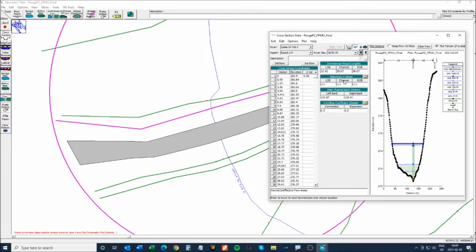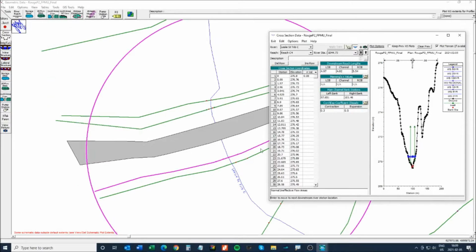Then we have 35.07 between this one and that one, and then 4.82 between these two. So together that's 5.67 plus 35.07 plus 4.82. It's 45.56, and we know that the new culvert is about 46 meters.